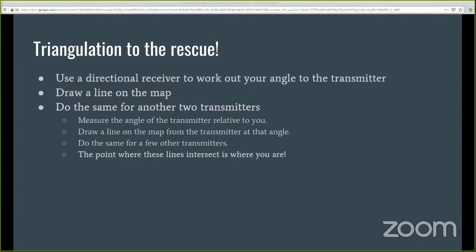So this is done quite regularly for radio orienteering or ARDF, amateur radio direction finding. The common form those take is actually fox hunting, which is where you have a transmitter sending a beacon signal, which you look out for and receive. Your directional antenna will obviously pick up a stronger signal in the direction of the transmitter when it's pointed at the transmitter. So you just follow the line effectively.